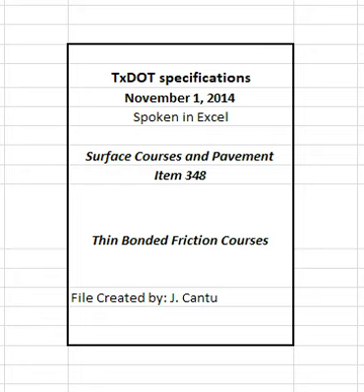Provide mineral filler, when used, that is sufficiently dry, free-flowing, and free from clumps and foreign matter as determined by the engineer, does not exceed 3% linear shrinkage when tested in accordance with Tex-107-E, and meets the gradation requirements in Table 3. Table 3. Gradation requirements for mineral filler. Sieve size and percent passing by weight or volume. Sieve size number 8 with 100% passing. Sieve size number 200 with 55 to 100% passing.